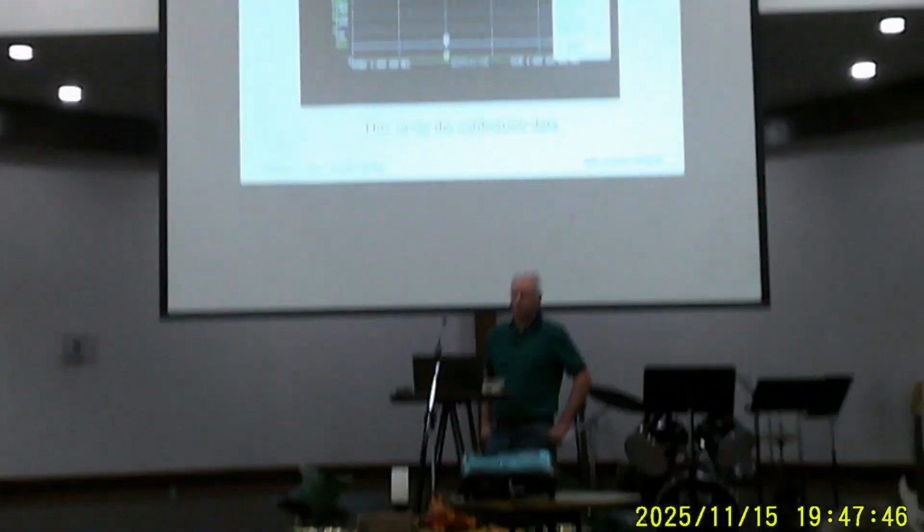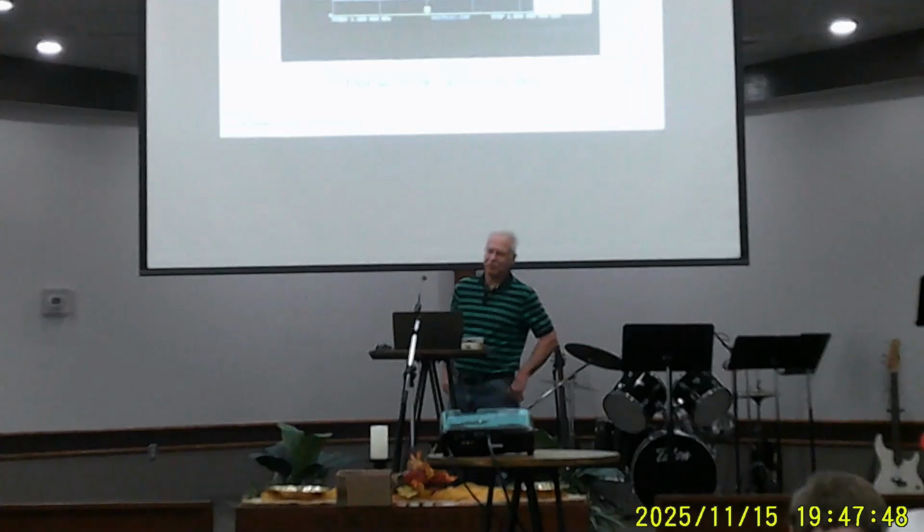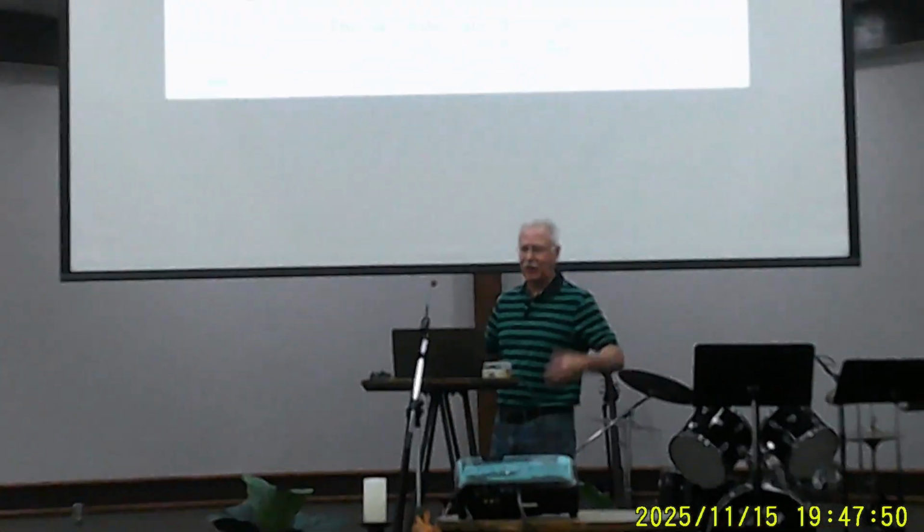Yeah, because I got a bunch of old RG59 that I had for some other project I was working on a long time ago, like a 1,000-foot roll. So I try to use it for stuff because I've got a lot of it. It will work for those, but it won't read exactly the values. And again, it's just math. You can correct for that. In fact, this one does have it built in. You can tell it that it's a 75 ohm system, and basically it just does the math to correct for the 75 ohms.